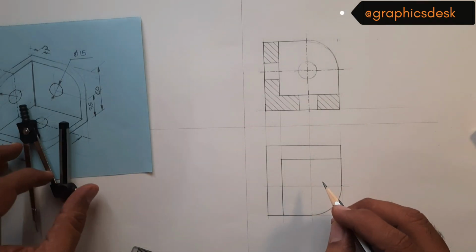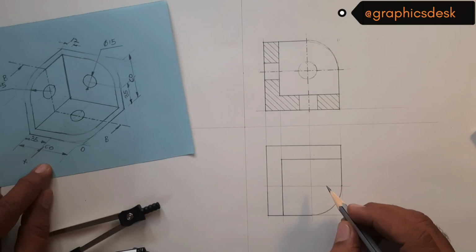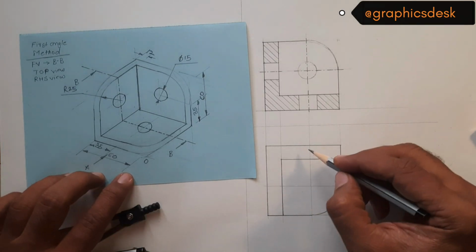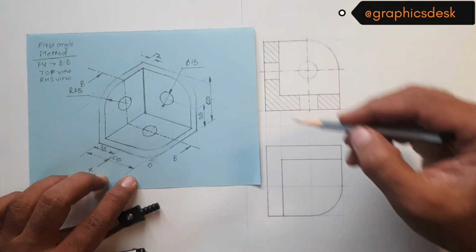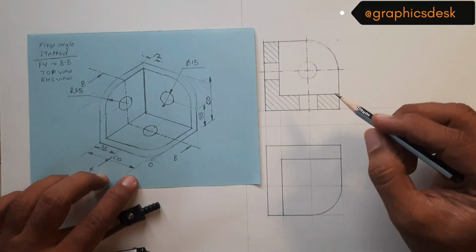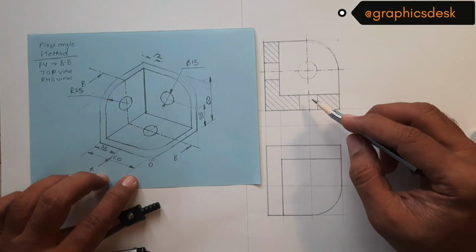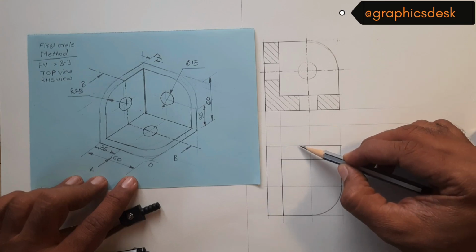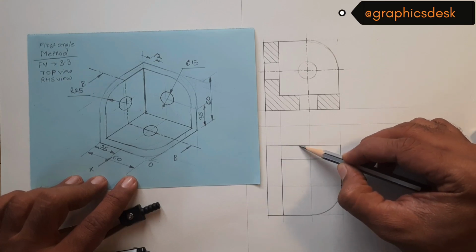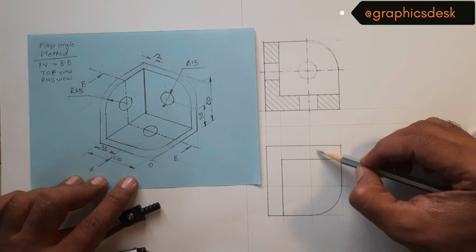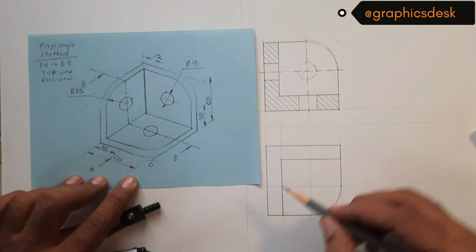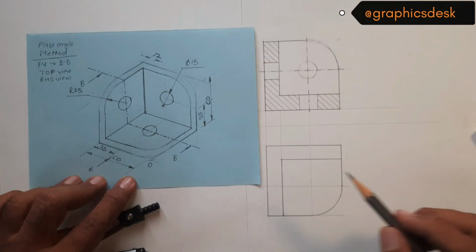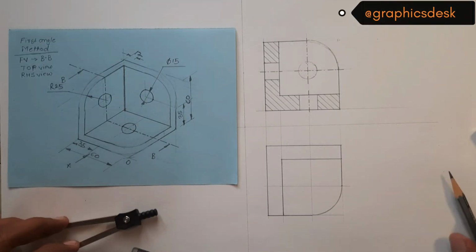So this is our top view, except we have to draw one circle here, and the circle on this face would be visible as dotted line. Now we are talking about dotted line here because this is not a section and no part of the hole will be visible, hence it will be dotted line. So a dotted line here and here representing a hole in this wall, and a dotted line here and here which will be representing this particular hole. So let me draw that.